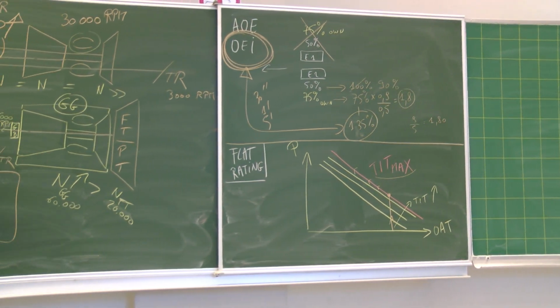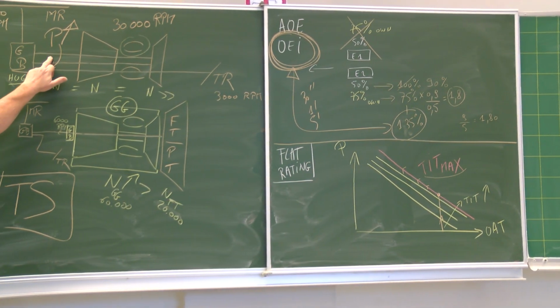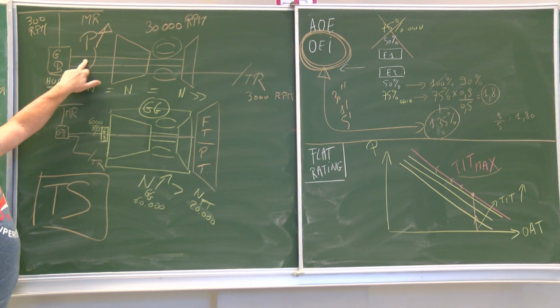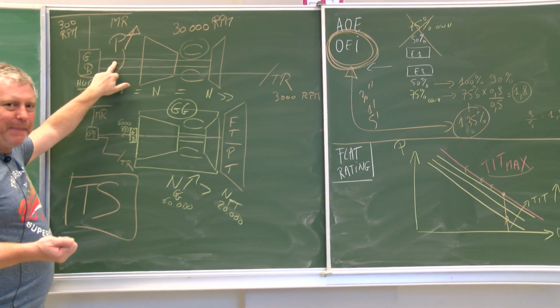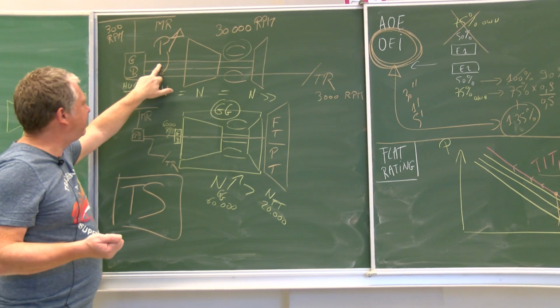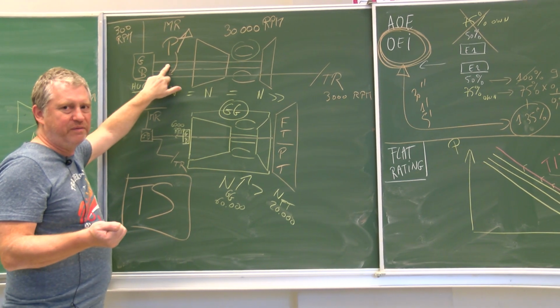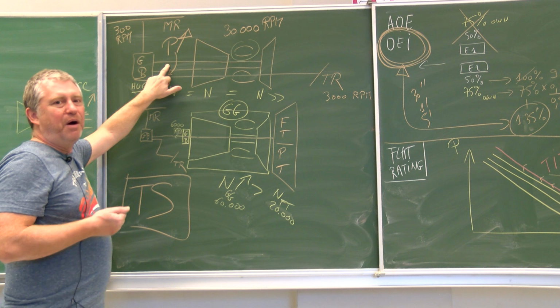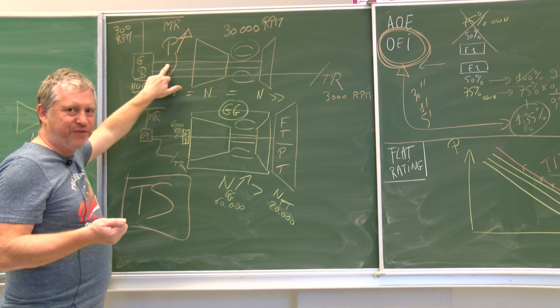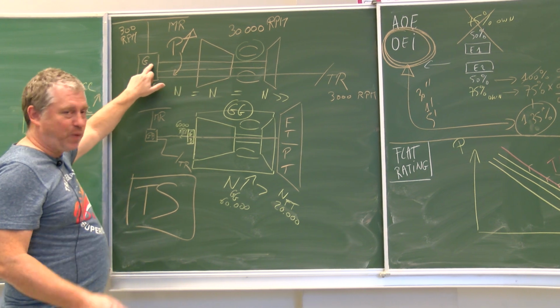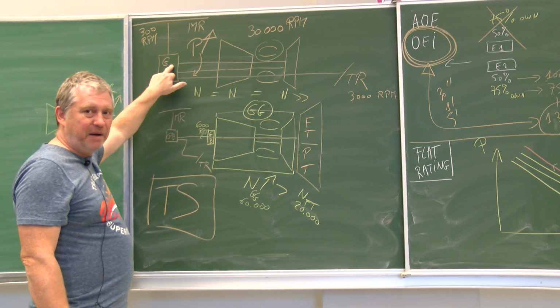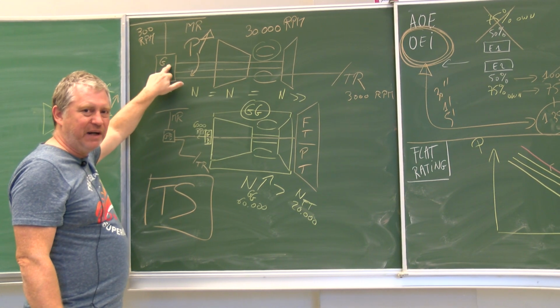You could break the shaft because there are 3 limits on a shaft, and one of them is the transmitted torque that could break the shaft. And the second one is the limit of the gears that you have here inside.